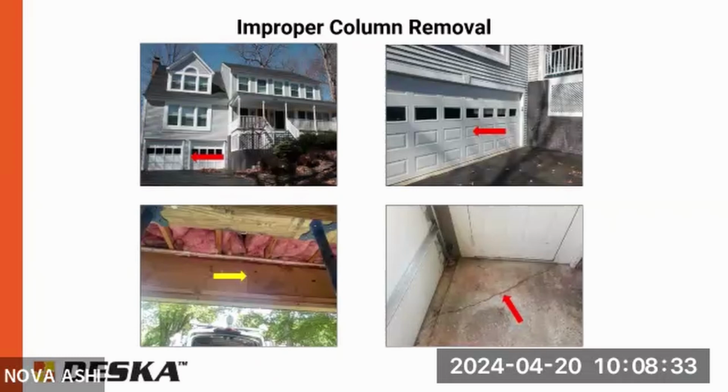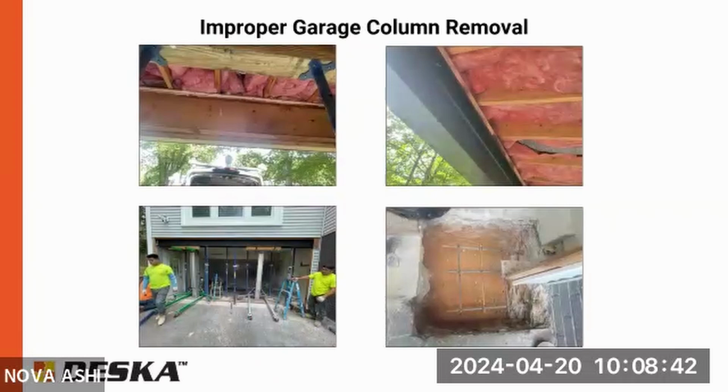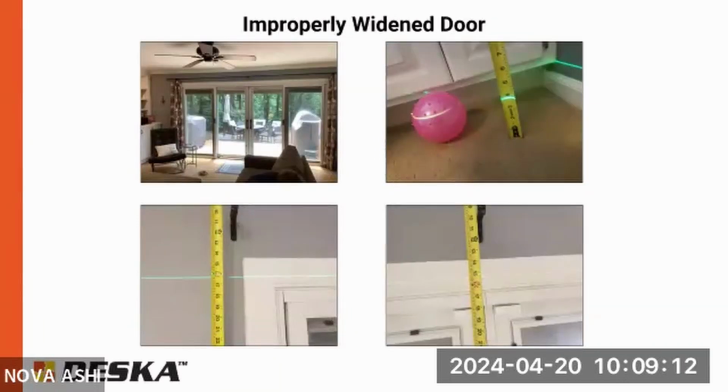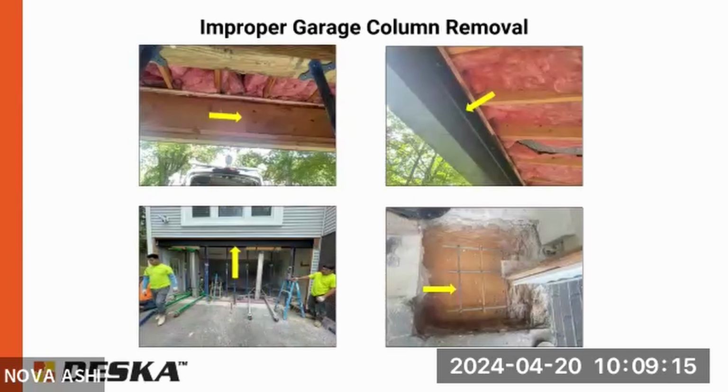And in this case, you can see it's supporting a floor, 2 floors above it, plus a roof load. So it's a pretty serious issue. We temporarily braced it. Obviously came up with the design first, temporarily braced it, and then reinforced the footings and installed I think it was about a 10-inch steel beam there to support it. The double 2x10s were only rated for like 15% of what the factored load was. Luckily, wood is very forgiving, so it's not typically just going to snap in half like a toothpick. It will bend quite a bit first, but it's a serious issue.